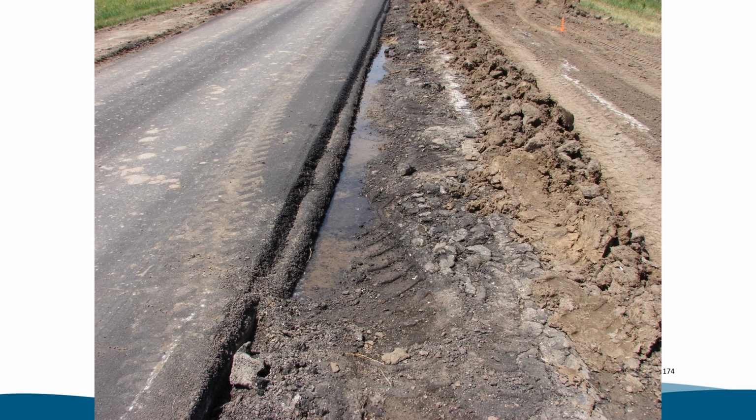While the laydown here looks good, notice the water along the edge of the surfacing. This can lead to a much bigger problem. Always maintain positive drainage and don't pond water next to the roadway, or it will go under the pavement subgrade and start breaking up.